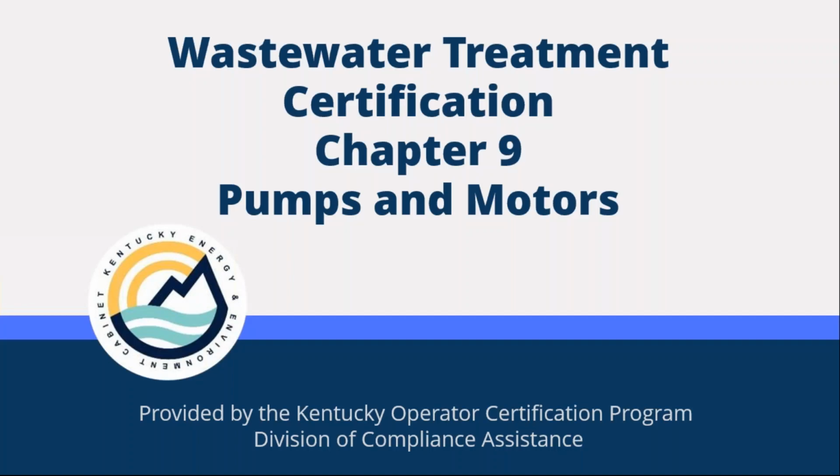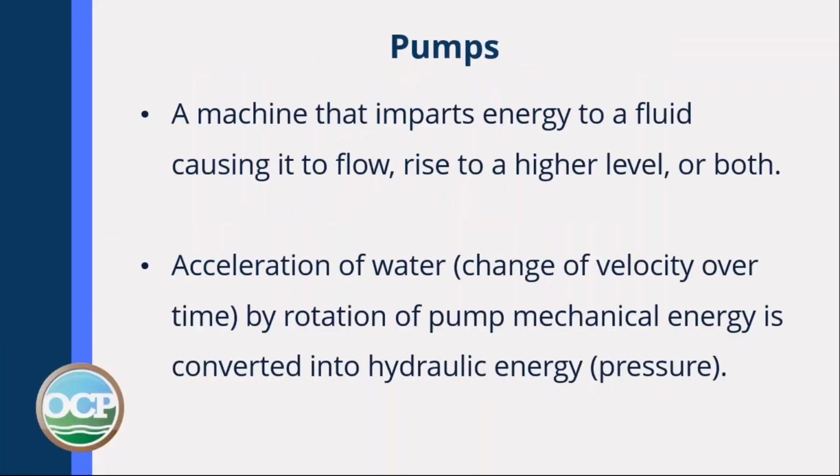This is wastewater treatment certification, Chapter 9, Pumps and Motors. A pump is a machine that imparts energy to a fluid, causing it to flow, rise to a higher level, or both. Acceleration of water, the change of velocity over time, is caused by rotation of the pump's mechanical energy being converted into hydraulic energy, pressure.